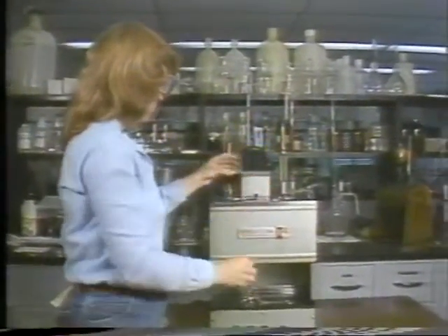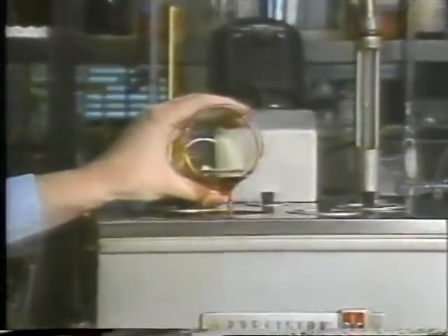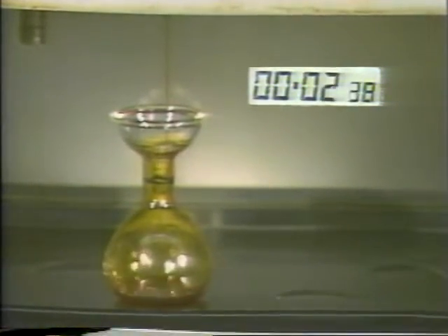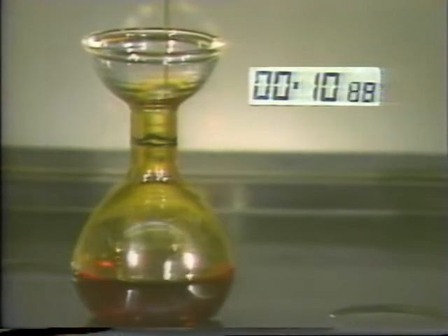To use the viscometer, an oil sample is first poured into one of the upper chambers. Then there's a waiting period for the sample to reach the same temperature as the oil bath. Next, a plug is removed from the upper chamber with the oil, allowing it to flow into the flask. A stopwatch is started the moment the oil is released from the chamber.